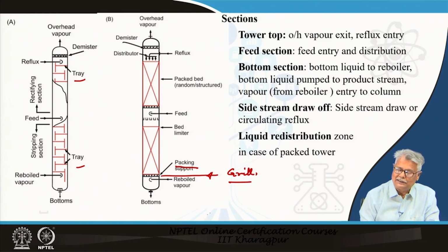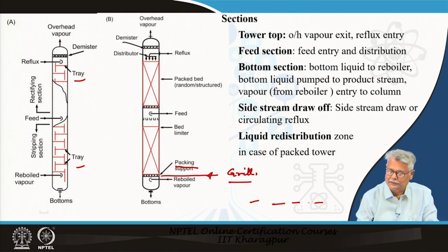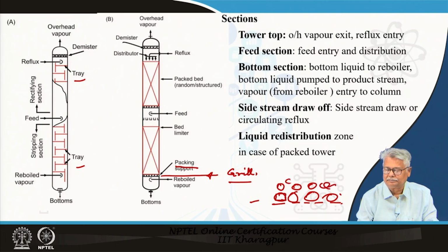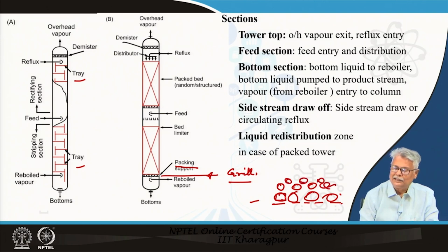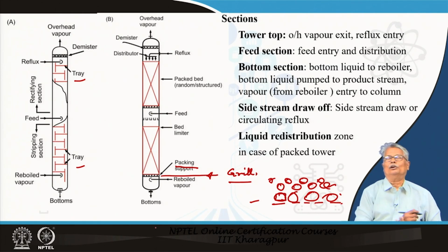Quite often what is done is you have this particular support, on that you have a set of bigger packings, on that you will have your smaller packings. The bigger packings will be ensuring that you have a fair amount of gas and liquid distribution among the smaller packings, and the smaller packings do not fall off. In fact, what we will always find is